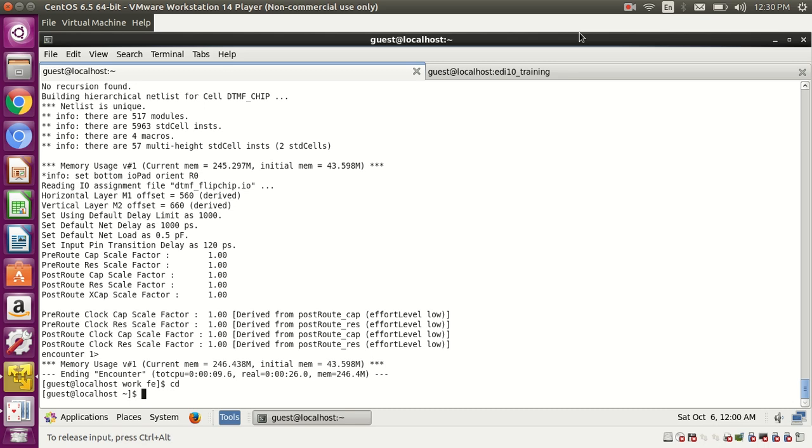SI means, theoretically, what we'll say is noise: whenever a signal is rising, if any aggressor comes down, the signal may glitch. That is the theoretical point for interview questions, but the tool will not calculate in that way. It will calculate when two metal shapes are parallel, or when M1 is there and M2 is there, in parallel, or they might intersect, so the tool will see that.